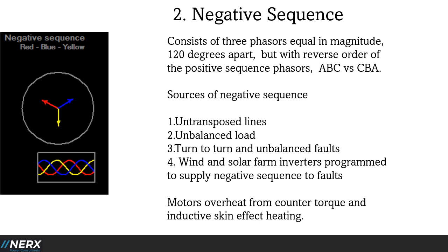One consequence of having negative sequence on the system during normal operations is that it causes motors to experience counter-torque and skin effect heating. This could force the motors to need to be derated.